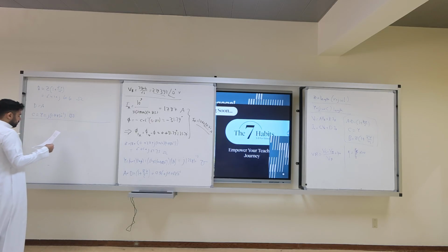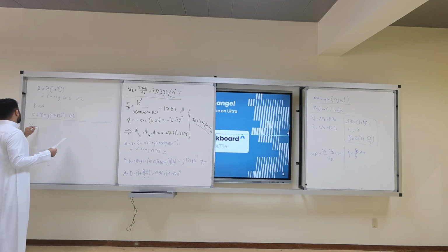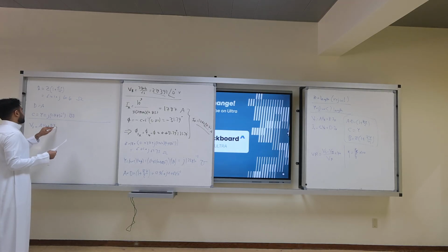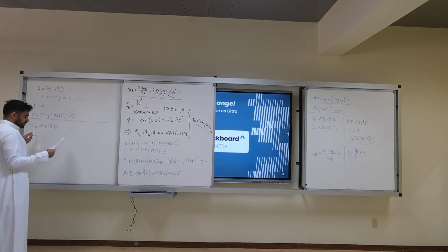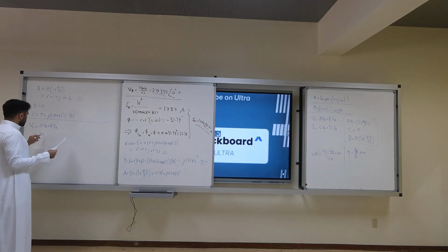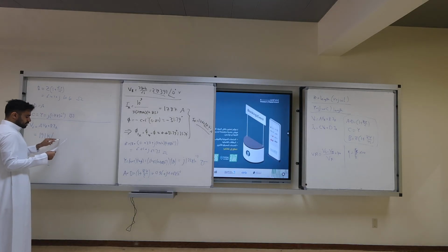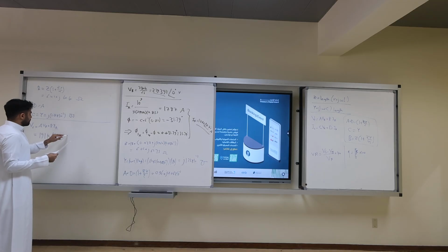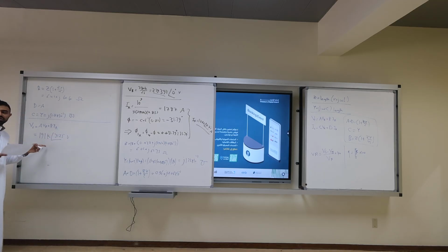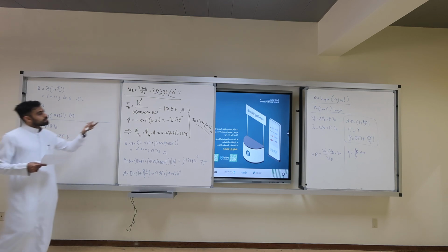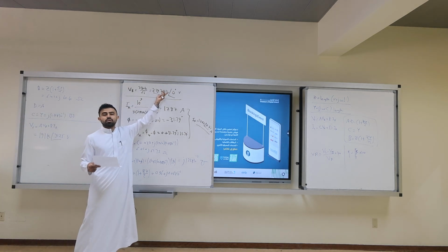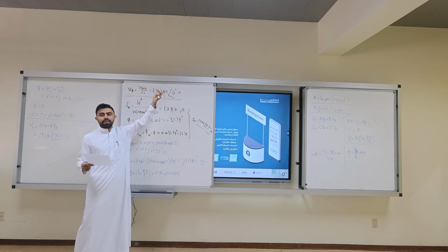So if you do Vs equal A VR plus B IR, you will end up to have 191 kilo angle 31.23 degrees volts. 191 kilo. Note that this voltage is smaller than VR because we have capacitive load, leading.